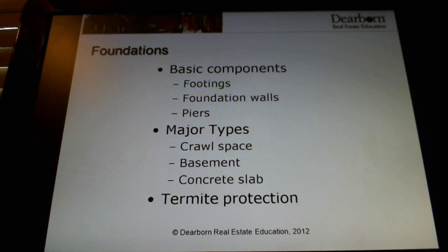Now, your foundation wall, in your book on page 378, is going to rest on top of the footings. It's going to be some type of concrete, brick, cinder block, some kind of masonry wall that sits on top of the footings and comes up out of the ground. Remember, footings are below ground, so the foundation walls are going to come up out of the ground. That's where we first get above ground.